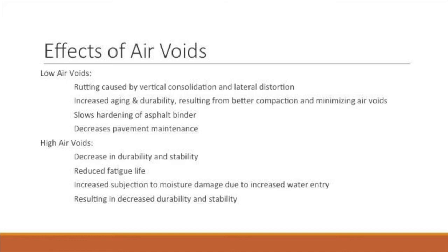Low air void content commonly causes vertical consolidation as well as lateral distortion. It can cause an increase in aging and the durability. This is from better compaction and minimized air voids. High air void content can decrease the stability of the asphalt and reduce fatigue life.